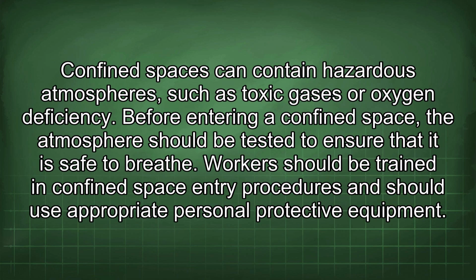Confined spaces can contain hazardous atmospheres such as toxic gases or oxygen deficiency. Before entering a confined space, the atmosphere should be tested to ensure that it is safe to breathe. Workers should be trained in confined space entry procedures and should use appropriate personal protective equipment.